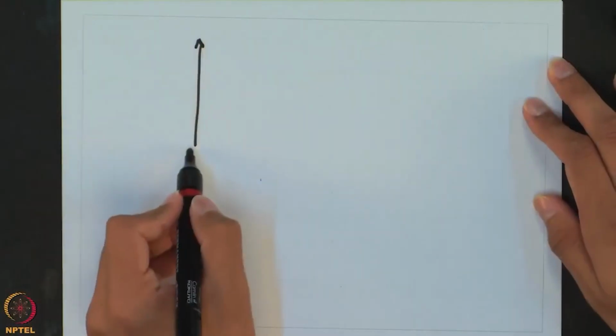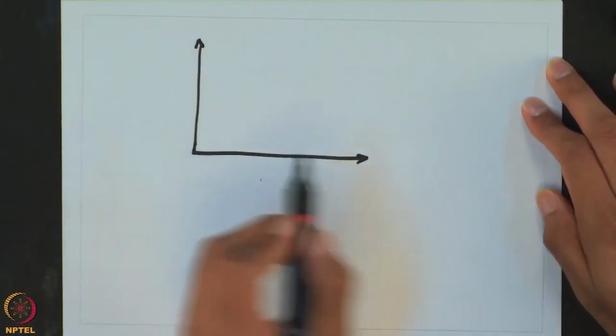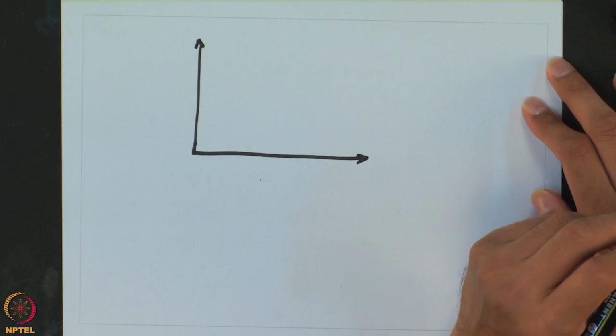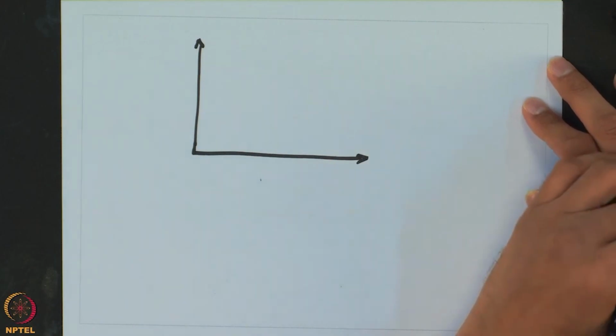We had seen this as a motivating example, and the order of the system is of the same order as the number of stages. So if the column has a large number of stages, this becomes a high order, 20-30, dynamic model, and it takes a very long time to settle.